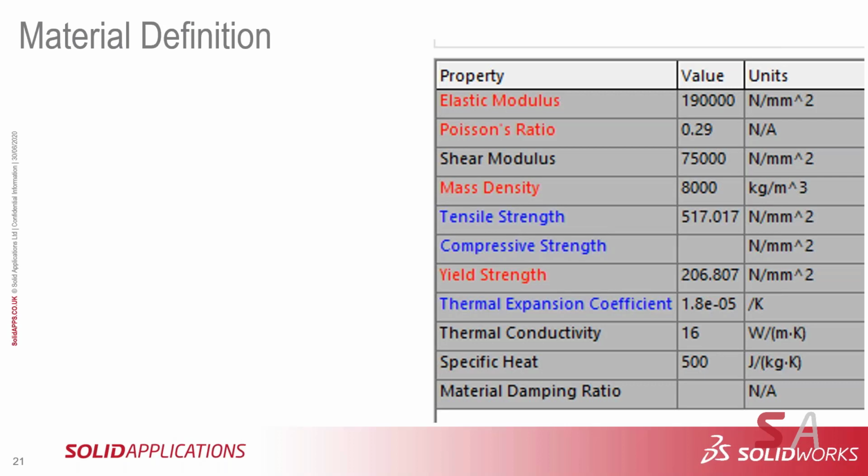And if your entire study result is below yield strength, it'll show up at the bottom, just telling you what the yield strength is. So if your highest stress is 160 megapascals, then it'll tell you that your yield stress is 206 and you're happy.